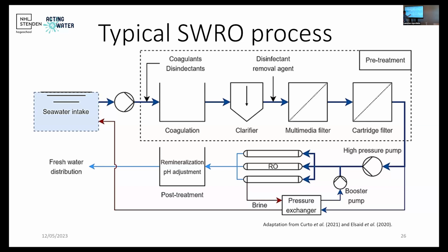As in thermal desalination, the membranes also produce quite pure outlets. So you need to remineralize. There is a necessity to add minerals back, and this can be done via a contact chamber. And depending on where you are, even after the addition of minerals, you still need a disinfection step. It's not represented here, but the chlorine addition aspect, because in some countries, for example in Brazil and most South American countries, you need to have a chlorine residual in the network. So after adding minerals, you have to have a chlorine addition system to guarantee a minimum residual of chlorine in your network.